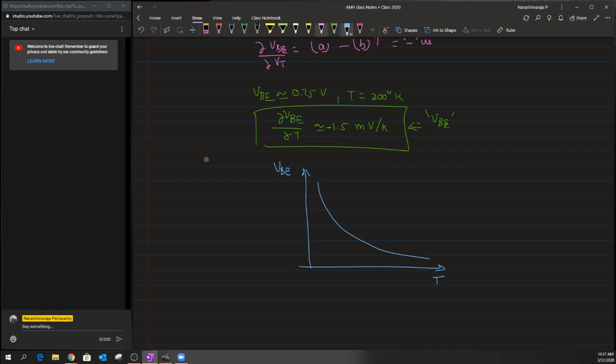It is not the graph we expected, a straight line, which we call CTAT. A circuit that exhibits such behavior is called CTAT behavior because the slope is constant throughout the entire graph. But when we look carefully at the slope of VB with respect to temperature, the slope changes with the value of VB I am picking and the value of temperature we are observing. So the slope is generally not a straight function.